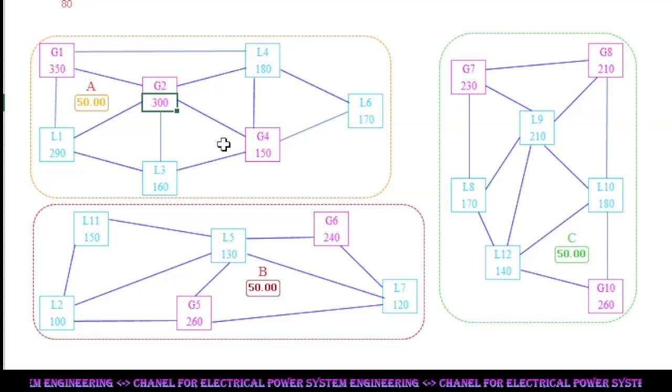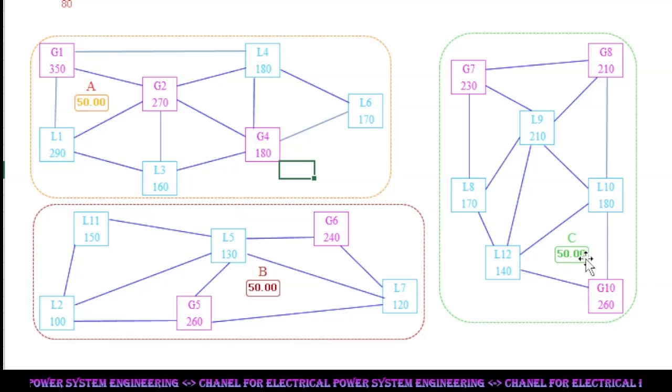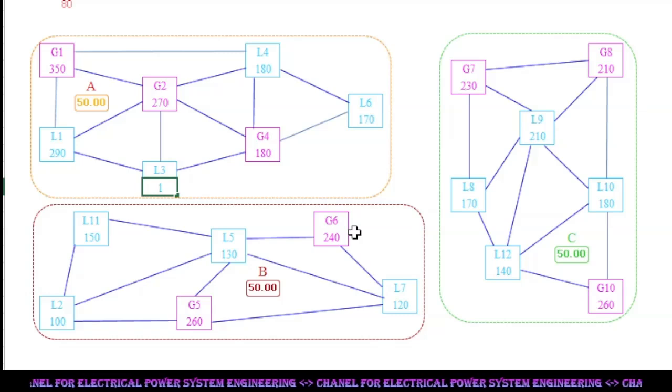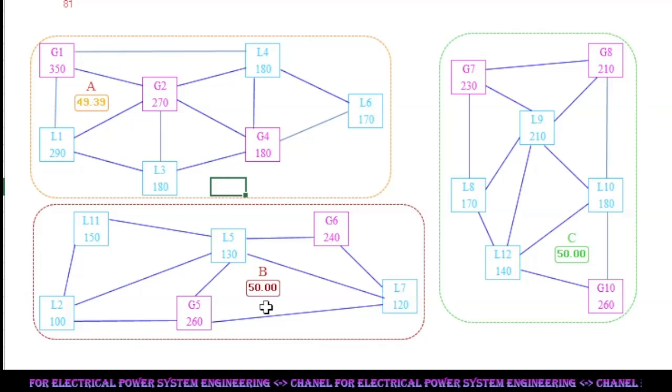Reduction of generation at any power plant causes frequency drop. Frequency improves when picking up generation at any other power plant in the same system. Similarly, rise of load at any load center causes a drop in frequency. Picking up some generation at any power plant improves frequency. Load shed at any center further improves frequency. During this exercise, frequency changes are observed in system A only, whereas the frequency of systems B and C has no change. Similarly, variations of load and or generation in system B or C have a local effect without affecting the frequency of other systems.